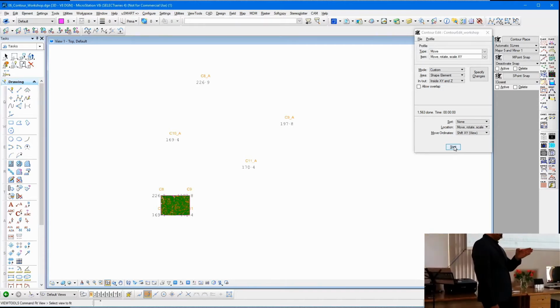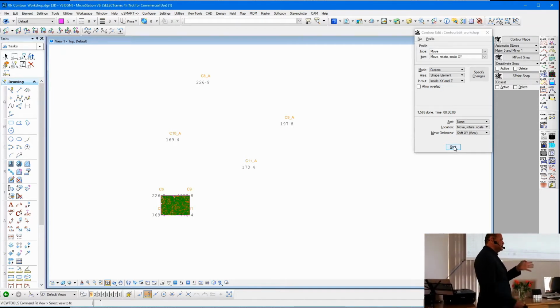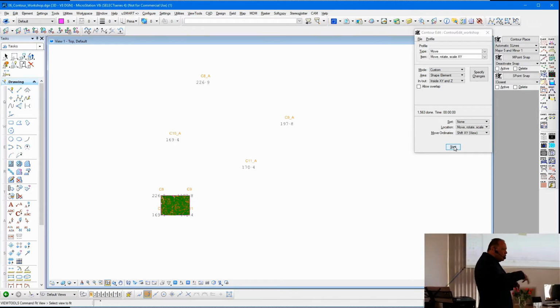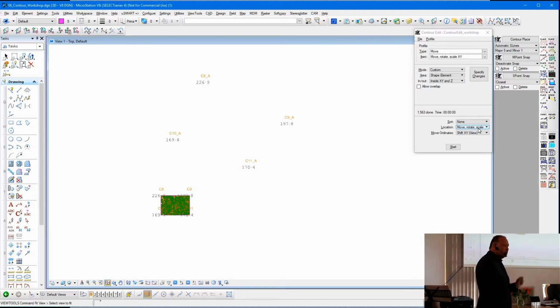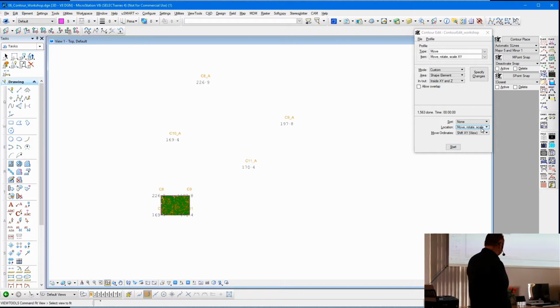Please don't confuse this with our C-point routine. Our C-point routine is another animal, and that's for warping things and fitting, and that's for when the national grid changed and there was a readjustment of the network and all of those options. This is a plane, as it says, okay, over there. Just read, location is move, rotate, and scale. Okay, that's what we're doing here. We're doing those movements with a least squares fit, of course, at the same time, because we've got 4 points now, so we've got redundancy, we've got more points than what we need.